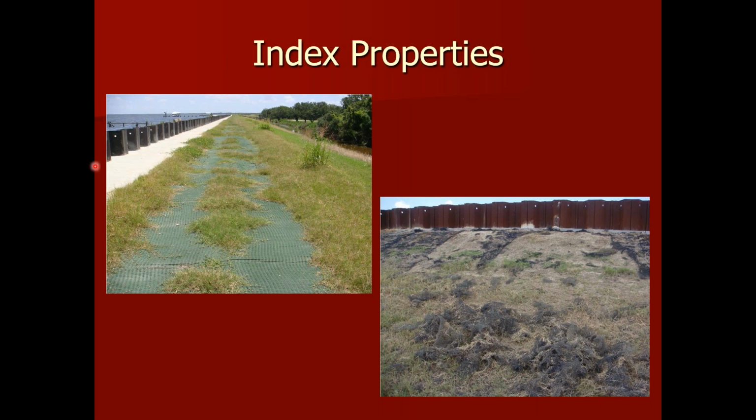You can see here on the left, we have a site that was used as a haul road along this levee so that they could bring the concrete trucks in and pour this T-wall that was put in place to dissipate the energy of splash over this wall. The water would come across and go down the protected side. This area was driven on with concrete trucks, and you can see the vegetation was disturbed there where the traffic was, but the mat is still in place.